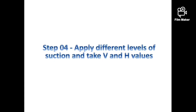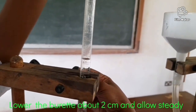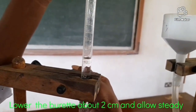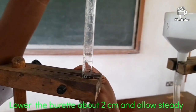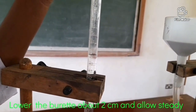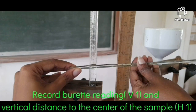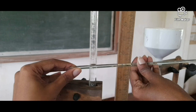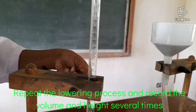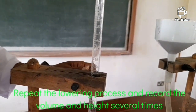Step 4. Apply different levels of suction and take V and H values. Lower down the burette to change about 2 cm of the reading and allow it to become steady again. Record the burette reading V1 and the vertical distance to the center of the sample and denote it as H1. Repeat the lowering process and record the burette readings and heights several times.